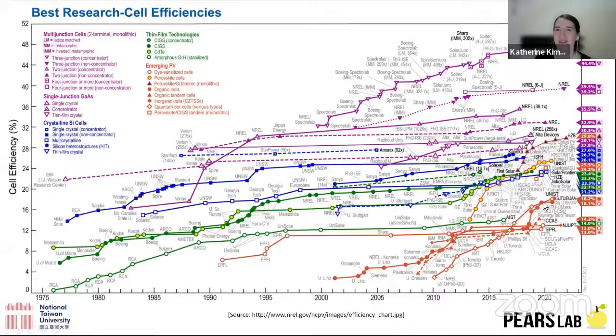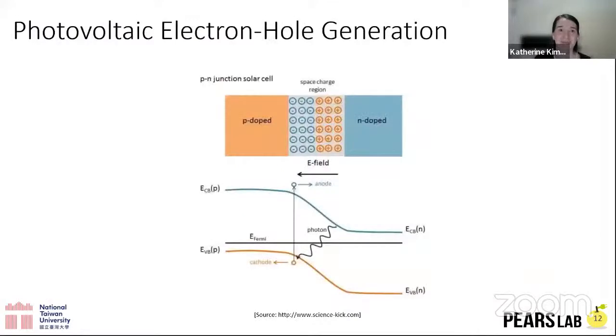but notice they're also a little bit lower efficiency. So whenever you're choosing the type of solar cell for the application, you have to think about form factor. Do you need a rigid cell? Does it need to be behind glass? Does it need to take a lot of temperature? Does it need to be flexible? What's the cost point? Things like that. Those are resources. You can look up more information on that if you're curious about the cells.